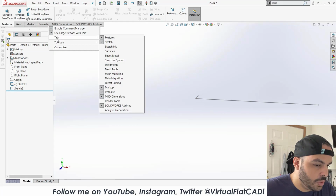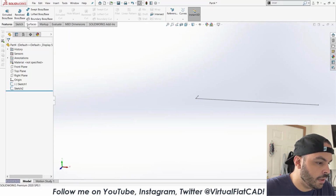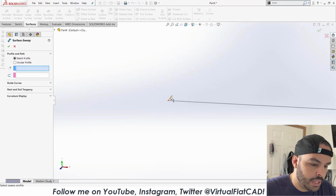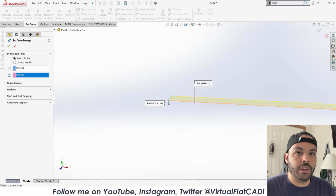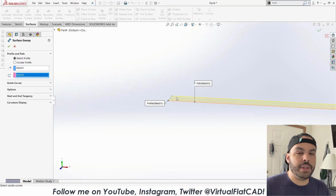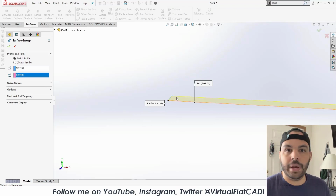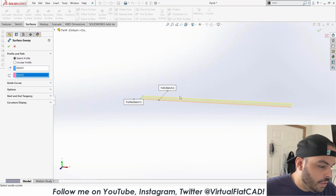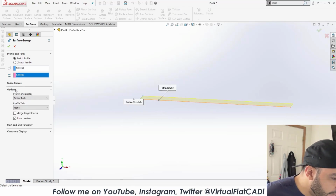It's kind of strange, right, to not use the helix tool, but if you go to surfaces, so I'm gonna bring my surfaces tab up, we're gonna go for a swept surface, and we're gonna sweep this short line along this longer line. The important thing, the key to make this work, is that the two endpoints need to be touching each other. So in this case, I just snap to the origin to make sure that they're in the exact same location in 3D space. But if you were building this somewhere else in the part file, you might have to put a pierce or even a coincident relation or something of that nature.